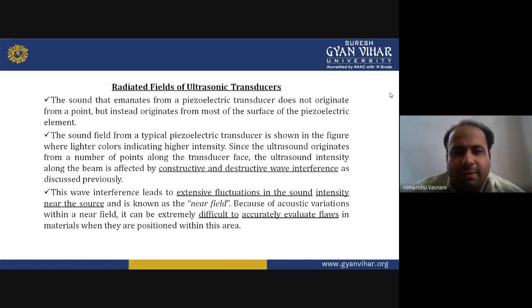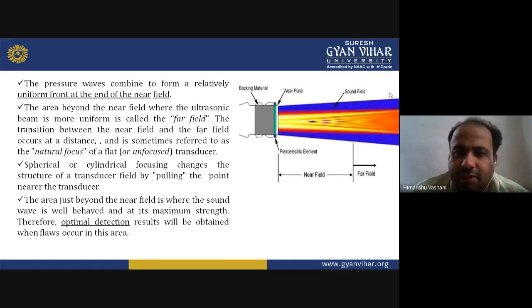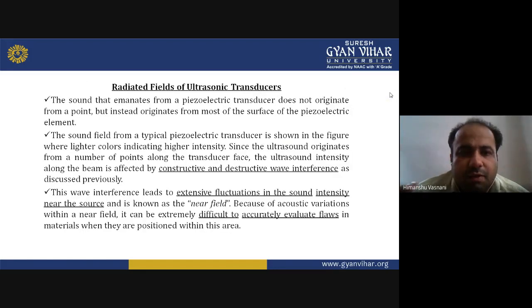The sound that emanates from a piezoelectric transducer does not originate from a point, but instead originates from most of the surface of the piezoelectric element. The sound field from a typical piezoelectric transducer you can see in the figure, where lighter colors indicate higher intensity.